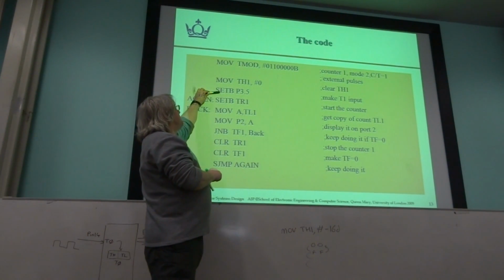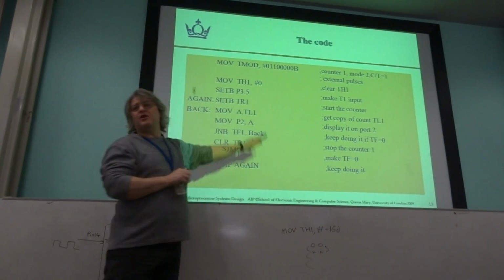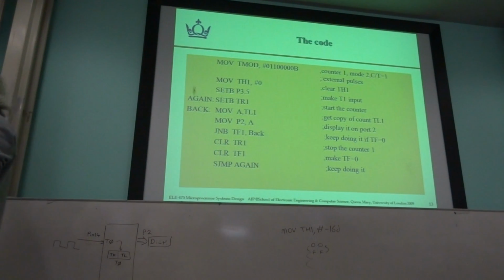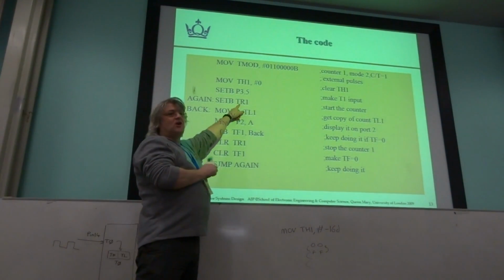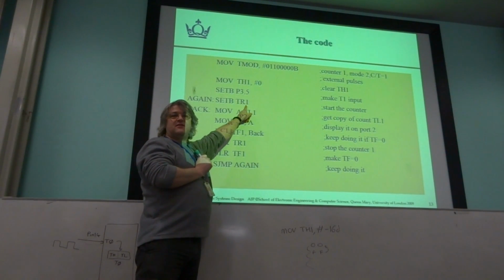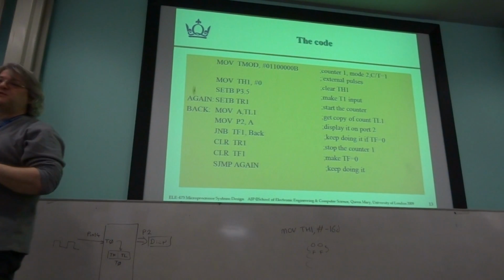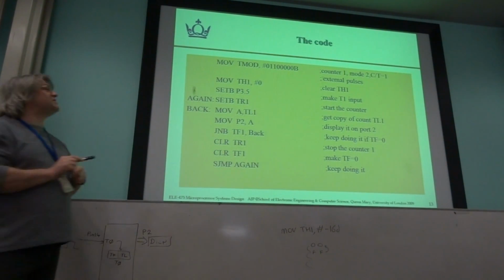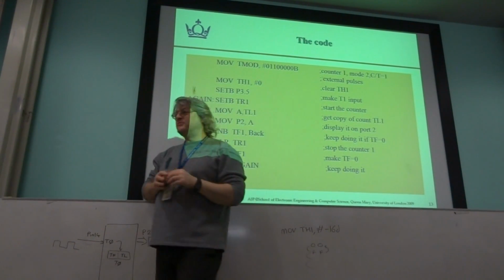Having done that, we've effectively pretty much initialized everything, and then at this point here we've switched on the timer itself. You'll notice that TCON is a register that's bit addressable. So I haven't had to write a whole byte to the TCON register. I can actually talk to individual bits. You can't do that with the TMOD register. The TMOD register, you have to write a whole byte at the same time. It's not bit addressable.